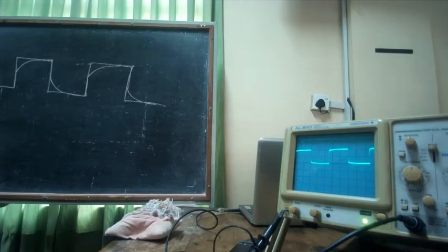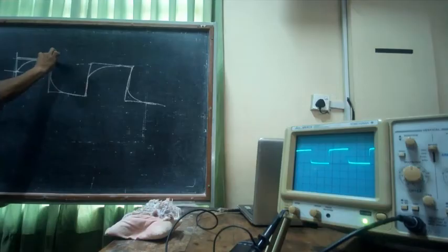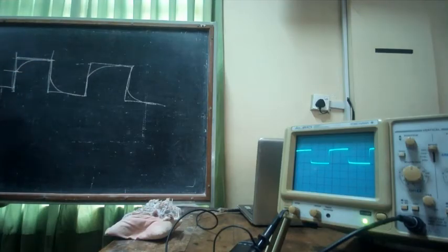Now the reason for that is, edges are high frequencies, these are low frequencies like DC, right? At high frequencies, the dominant factor is the capacitor. So the capacitor decides what this voltage ratio is, and decides the initial voltage of this signal. At DC, the resistors decide what the ratio is. Because we already know that it should be 10, it achieves it. But because the capacitor ratio and resistor ratio are both not 1:10, we have something like this.